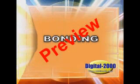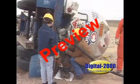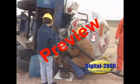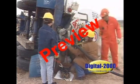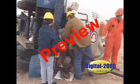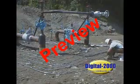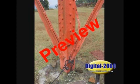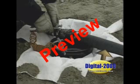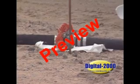Bonding. Bonding physically connects two conductive objects together with a bond wire to eliminate a difference in static charge potential between them. You must provide a bond wire between containers during flammable liquid filling operations, unless a metallic path between them is otherwise present. Grounding. Grounding eliminates a difference in static charge potential between conductive objects and ground. Although bonding will eliminate a difference in potential between objects, it will not eliminate a difference in potential between these objects and earth unless one of the objects is connected to earth with a ground wire.